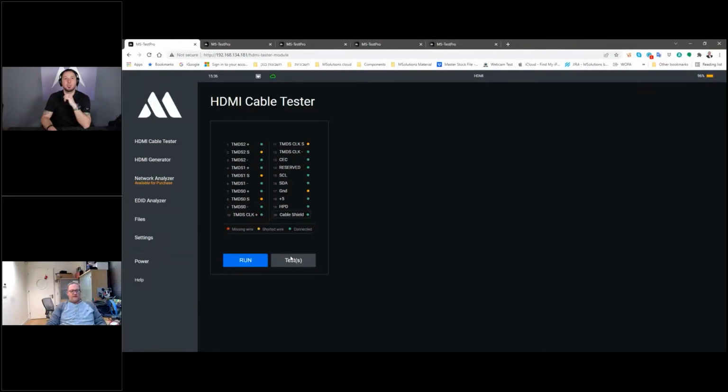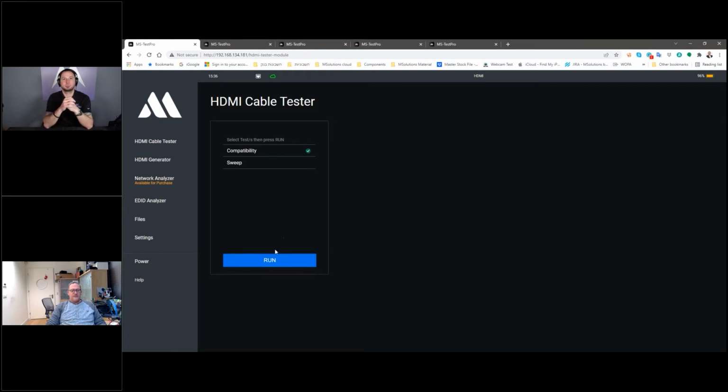Good. Okay. Thank you for that. Welcome. Let's see the compatibility. As you remember, we have seen shorts on the GND, on the shielding, and all the shielding also shorted. So these are the interesting results that we are seeing. 8K on this type of cable will not work. It will fail. 4K with HDR, which is 18 gig, as I mentioned to you also, will not pass because of what we have seen.